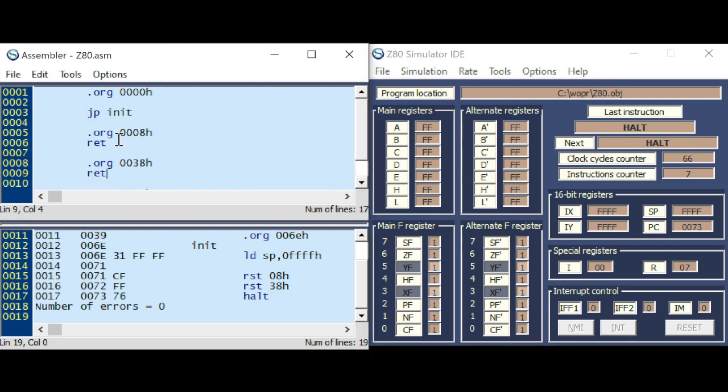So here in the interrupt routine you would normally jump to another place because there are only 8 bytes. You have only 8 bytes here. The next entry point would be at address 0010, and that's not enough for normally a program. So here you would normally jump to a different place, but for this purpose I will demonstrate it here, loading the accumulator with 8, and here loading the accumulator with 38.